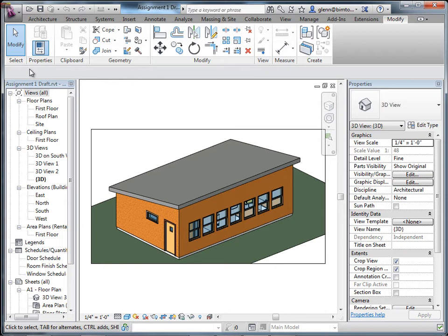One of the first things you want to think about as you're trying to lay these things out on sheets is all the different views you might want to create relative to the different audiences. There are all these different people who want to use the information, so you start thinking not about a single view that serves all needs, but about what information different people need to see. And views are cheap. We can duplicate as many views as we want and crop, filter, or add annotations to make them custom to what we need. There's no reason you have to keep everything as one big view.